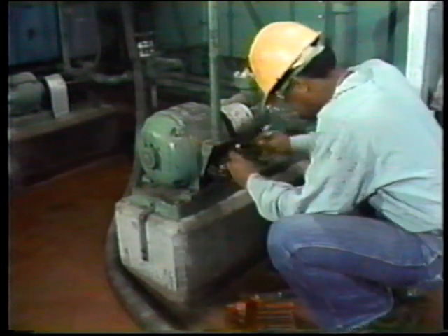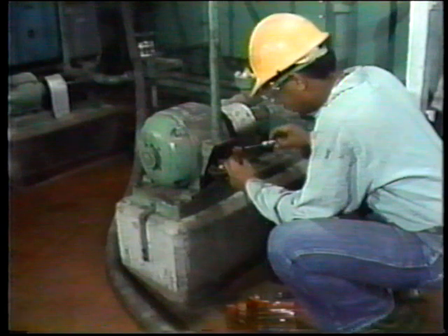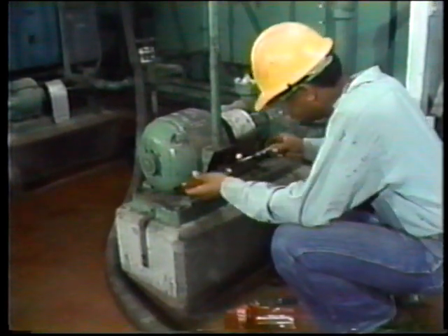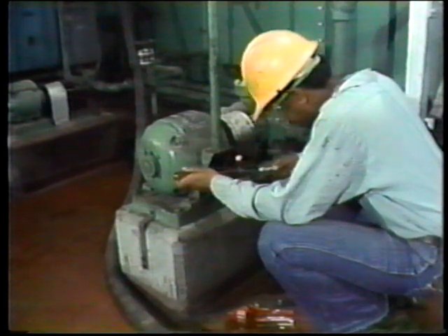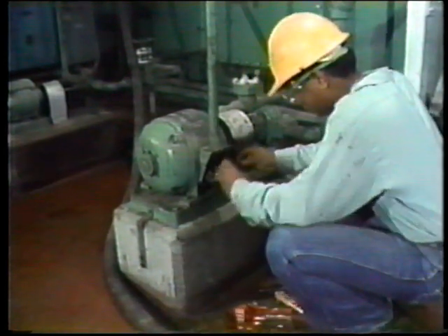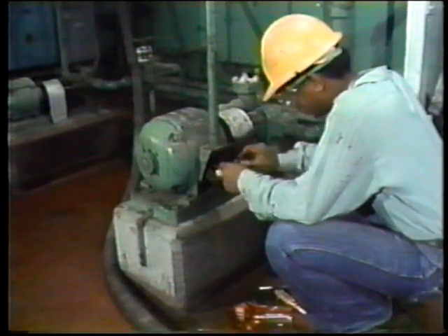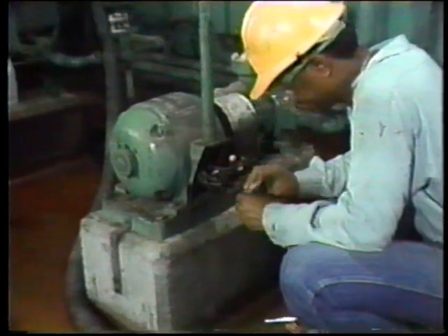After the hardware is in place, Bill has to rebuild the insulation. This insulation will have to meet the same voltage requirements that the original insulation met. So Bill used the same selection process that he used when he chose the tape to rebuild the insulation around the splice. He considered voltage, temperature, and environment.